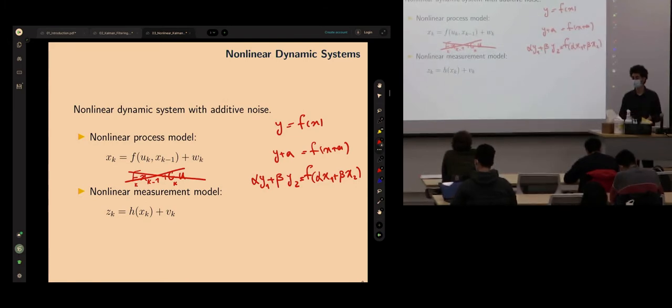If it's nonlinear, you're not going to have this structure carried over to the output, which makes it, in general, difficult to know what to expect. But depending where you are in the domain, the behavior of the nonlinear model can change as well, which makes it super challenging. It depends on your operating point. If the robot is moving fast, you might get a different behavior. If the robot is moving slow or turning, you might get a different behavior. Then you can expect different levels of accuracy and performance from your algorithm based on your mode of operation.